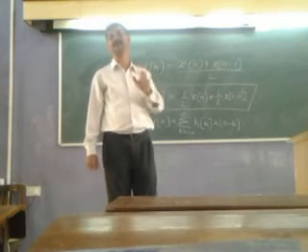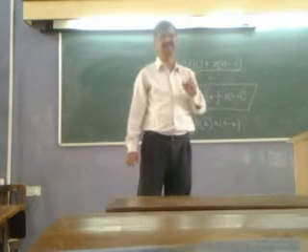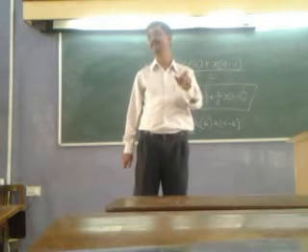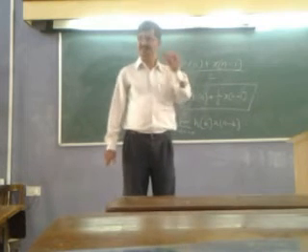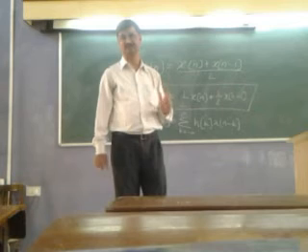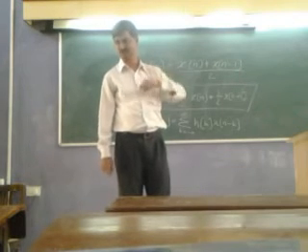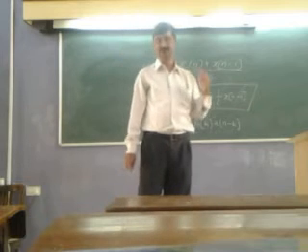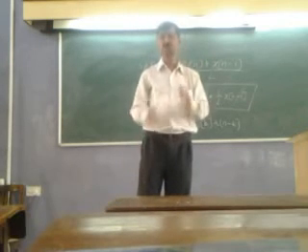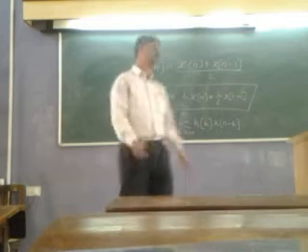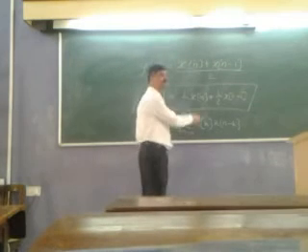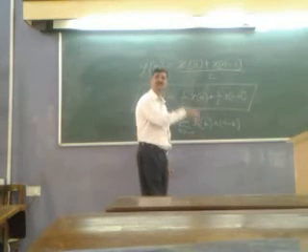But if n represents time domain, if xn is a sample sequence, it is not possible for me to predict what would be xn plus 1, what would be xn plus 2. Therefore, if the system is to be a causal system, to which we shall restrict for the time being, we must have all hk prior to k equals 0 must be 0.